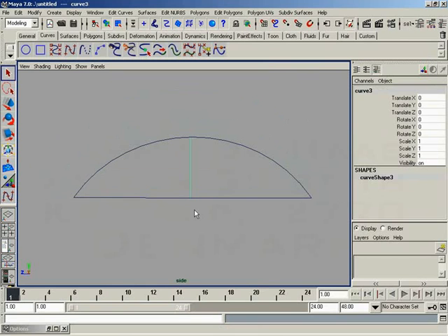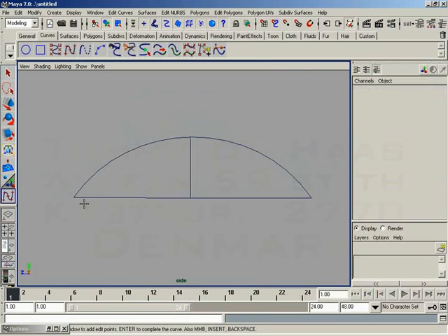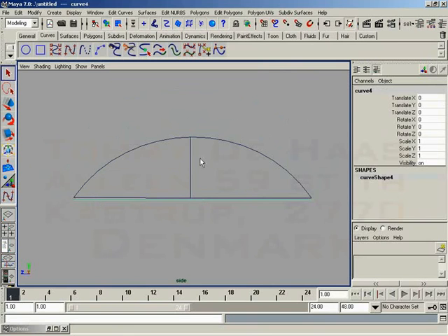What the chord height ratio is, it's a ratio of the chord height against the chord length. The chord length is the distance between these two vertices here and here. So you put these two measurements against one another, the measurement of this distance being the chord height versus the measurement of the length between the two vertices of this edge, and you end up with a ratio. Now, internally, that means that the lower the ratio goes, the more tessellation you should be getting.